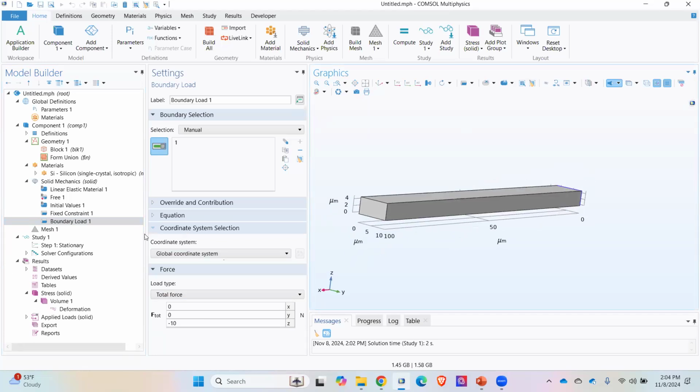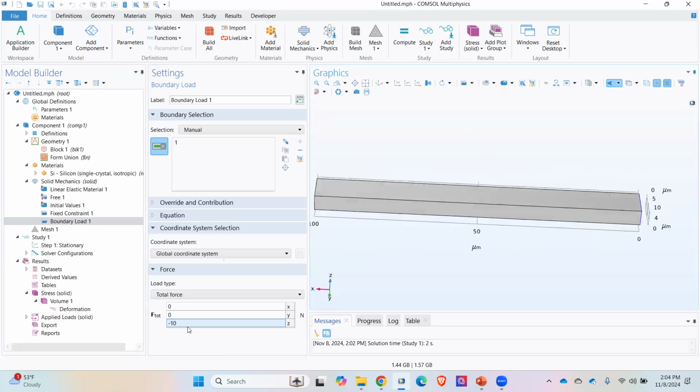Yeah, sorry. So as I told you earlier, you can put your expression here as well, right? So let's say since you are applying a force here, what will happen if I just write F instead of 10? If I just write F, it turns red. See, if I put my cursor there, it will show unknown variable. So that means you have not defined F.